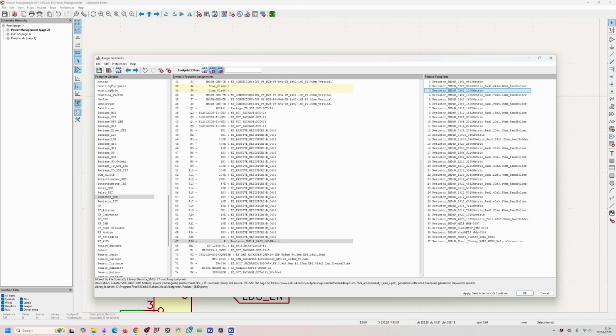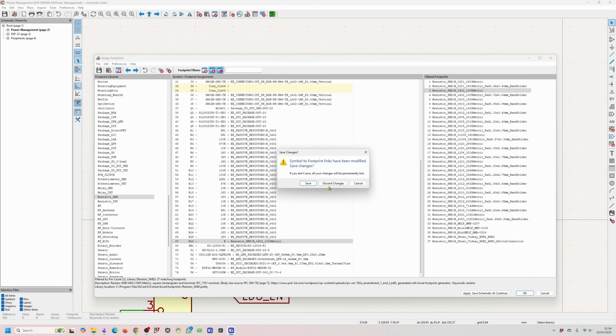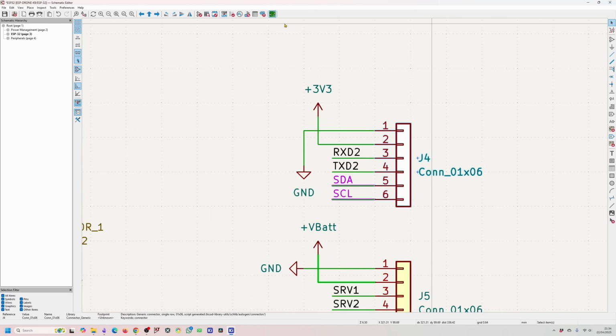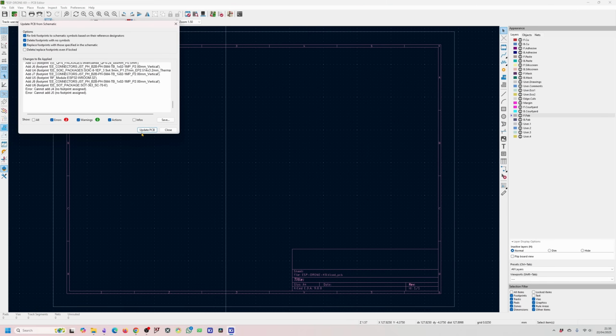And if you have any missing footprints, and when you transfer over to the PCB design side, which I'll show you now, you can see I've got two symbols that don't have any footprints assigned. Now if I go into the PCB design side and I load in my components, you can see KiCAD has flagged an error telling me that two components don't have a footprint.